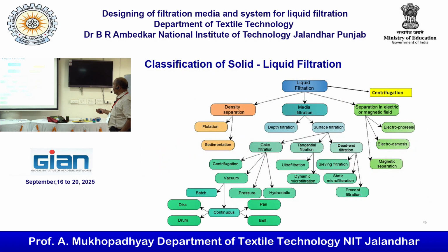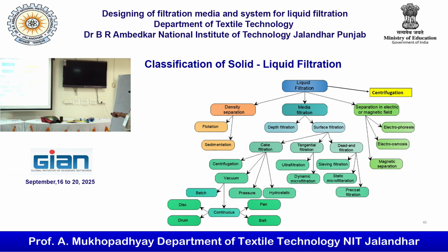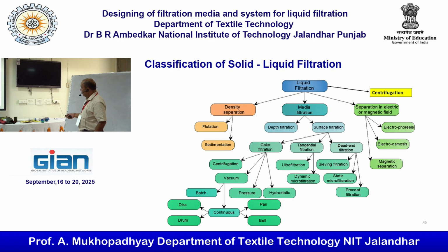Now if you see the classification of solid and liquid filtration, this part is basically separation, not filtration. Flotation, sedimentation, density separation, this whole part comes under separation. Again, if you see this part: centrifugation, separation by electric and magnetic field, electroosmosis, magnetic separation, electrophoresis. These are all again separation. Only the media is required for this whole application, the inner center one.